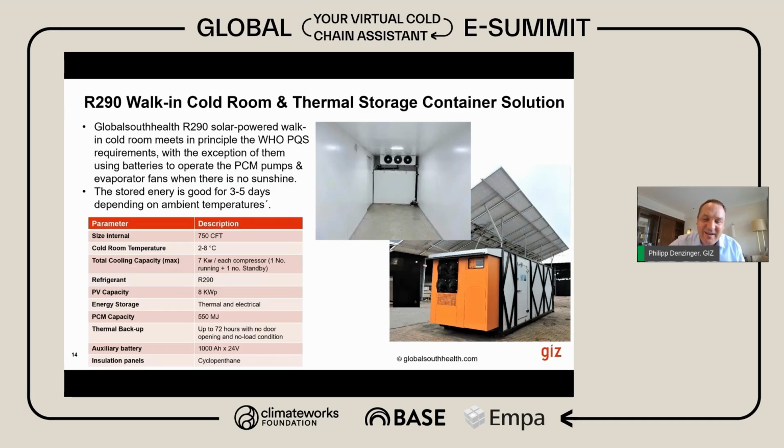Because the main challenge, and I've been working with the World Health Organization and PQS for many years, is that they only accept direct solar drive if there's no battery, and we still have to work on that, because of course you need to have a small battery for the thermal storage, for the ice water or whatever, and the fan. So the PQS needs to be changed there, in my opinion. When it comes to direct solar drive vacuum coolers, it's a different story, but for walk-in cold rooms, this won't work. It's a nice container solution, that's why I'm presenting it.